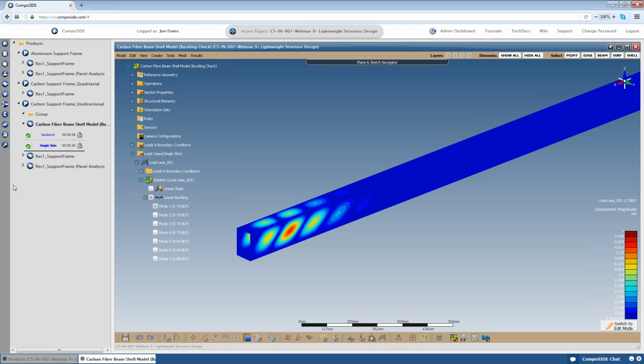What I can do is add thickness to the webs, but I don't want to add too much weight and therefore increase the cost quite a lot. So the other option would be to use a foam core. This is what I'm going to do. I've selected a 3A T10 foam, which gives me excellent shear buckling results, and it's a relatively thin core.